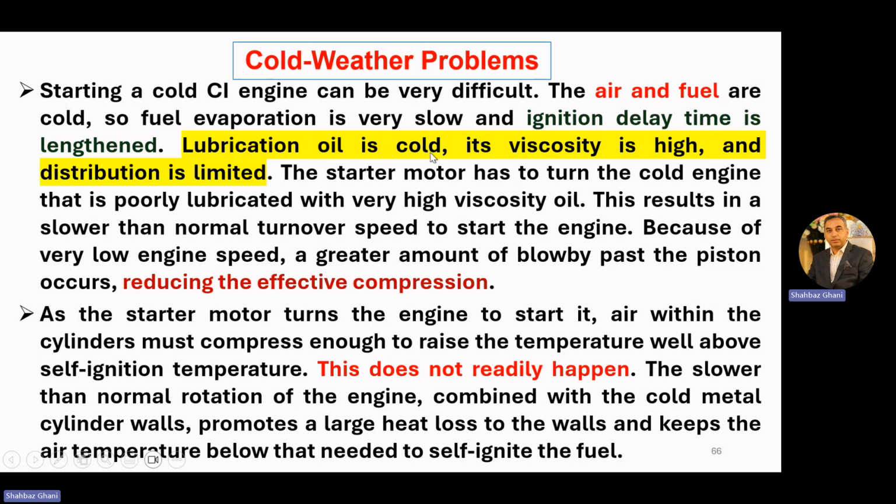Lubrication oil is also cold, its viscosity is high, and distribution is limited. So the starter motor has to turn the cold engine that is poorly lubricated with high viscosity oil. This results in a slower than normal turnover speed to start the engine. So more load on your self-starter and batteries.